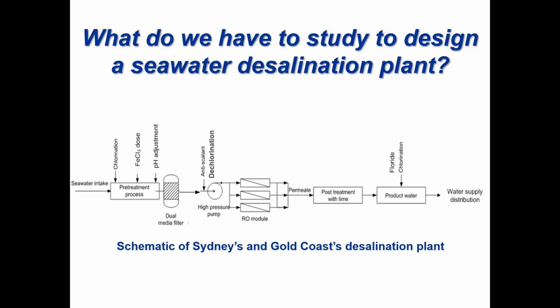After that, we have a dual media filter. The dual media filter filters with sand or anthracite, so particles can be removed by the media filter system. And after that, the next step is anti-scalant. As I mentioned, we will extract water molecules, so your salt concentration will increase to double.